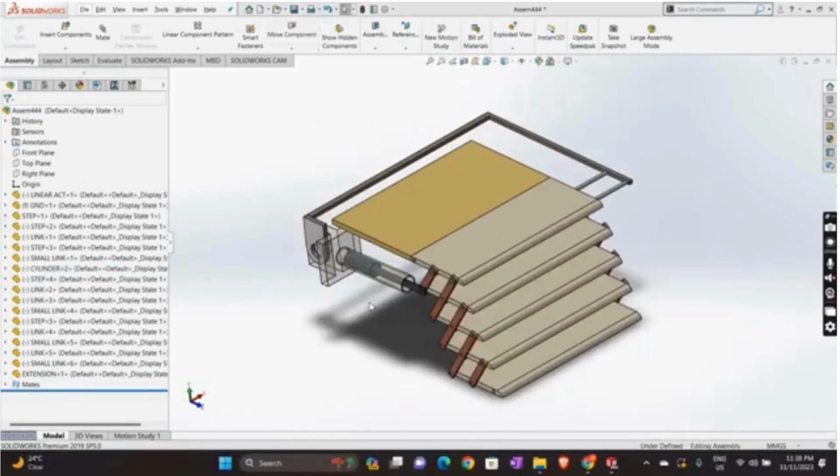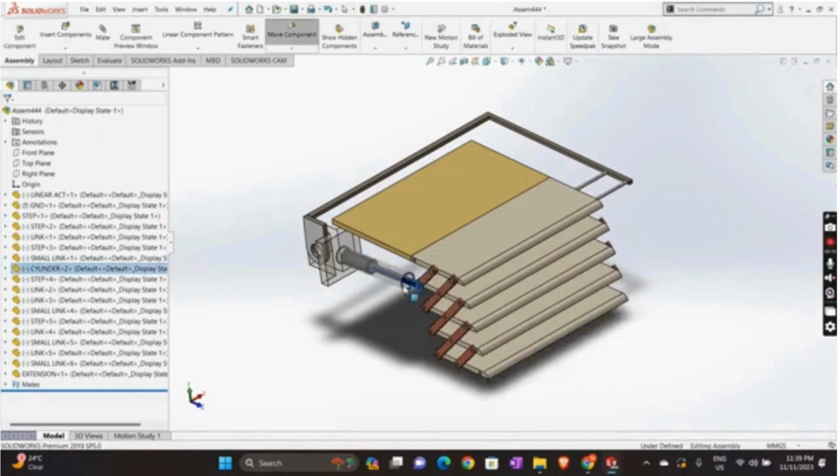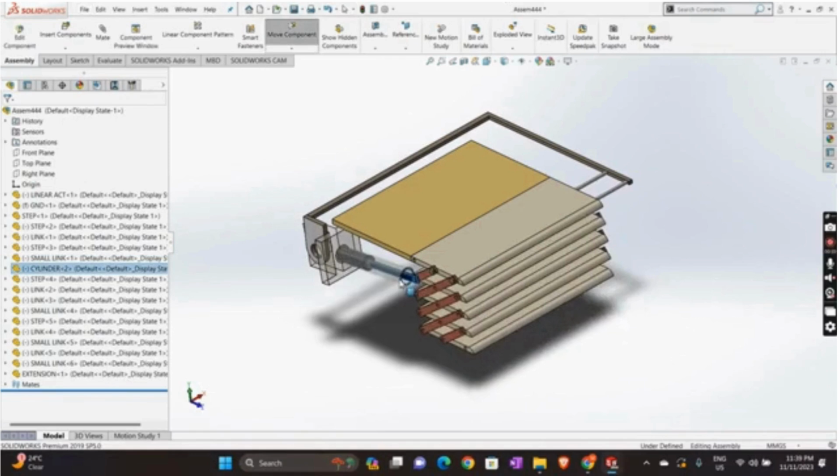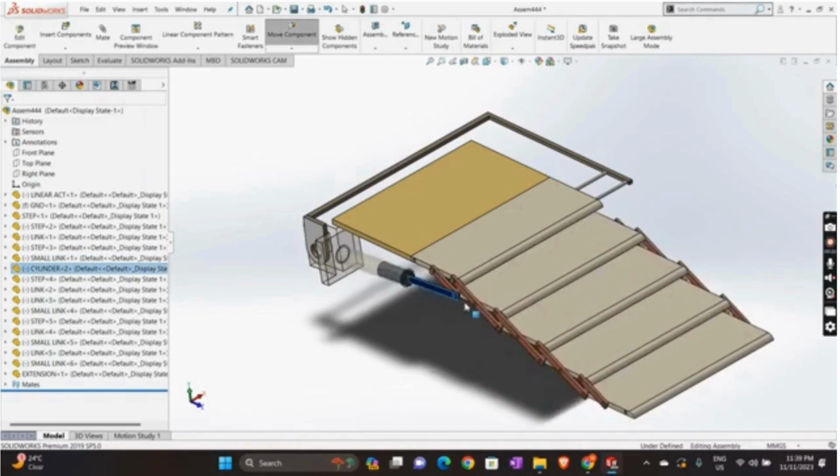So now let's move on to the mechanism and its working. We have used a double rocker mechanism. There are two dead center configurations which are noticeable here, due to which none of the links rotate completely but rotate up to a certain angle, beyond which they attain the dead center configuration, so as to limit the total movement of it, as you can see.